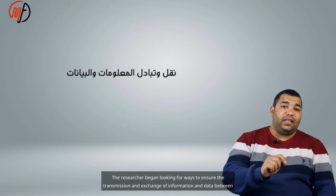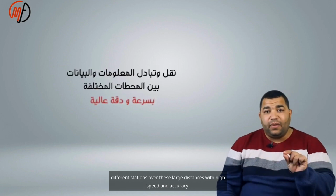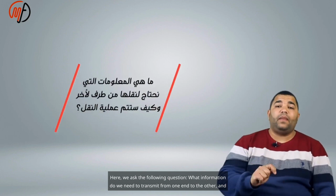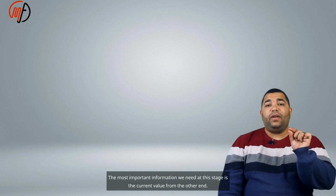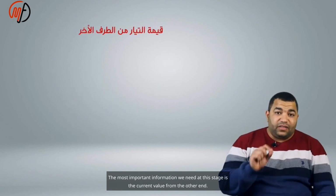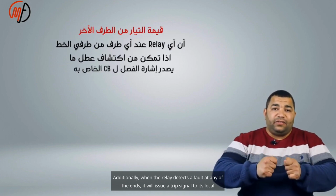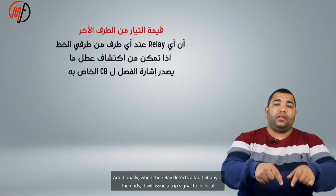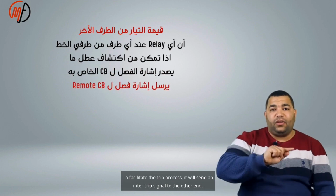The researcher began looking for ways to ensure the transmission and exchange of information and data between different stations over these large distances with high speed and accuracy. Here, we ask the following question: what information do we need to transmit from one end to the other, and how will the transmission process take place? The most important information we need at this stage is the current value from the other end. Additionally, when the relay detects a fault at any of the ends, it will issue a trip signal to its local circuit breaker. To facilitate the trip process, it will send an inter-trip signal to the other end.